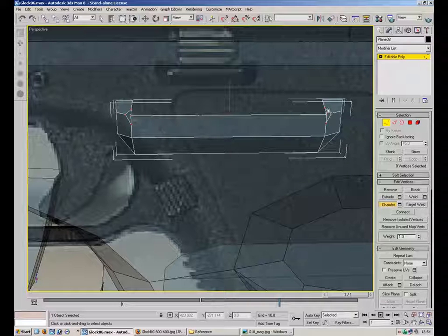Just going to chamfer those edges. As you can see, it's gone four ways. It's created an extra vert down each one of these edges, which is attached to the vert that I'm chamfering. And it's also created a bit of a mess. So if I pull that out, there's 2 verts perfectly on top of each other, and it'll be the same on the other side.